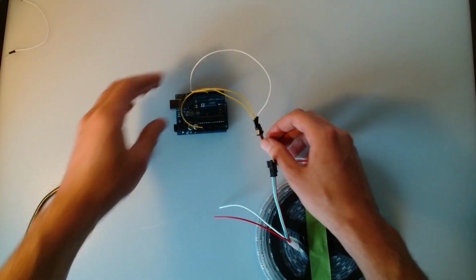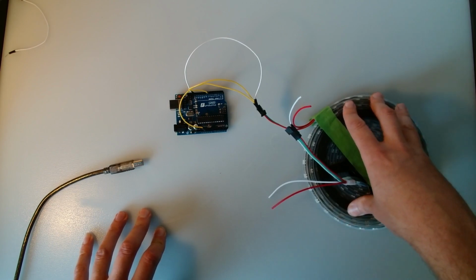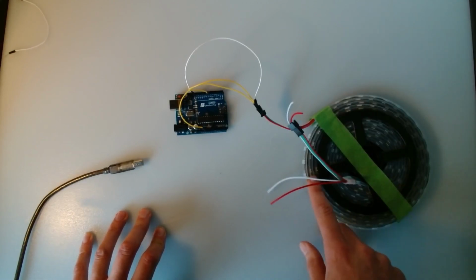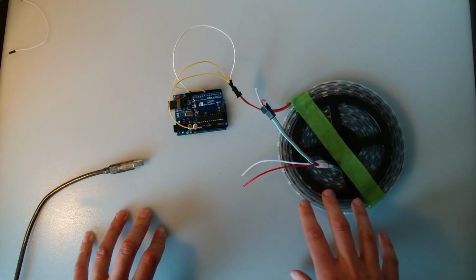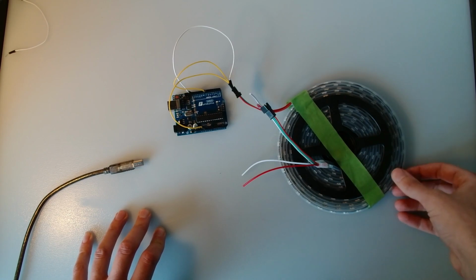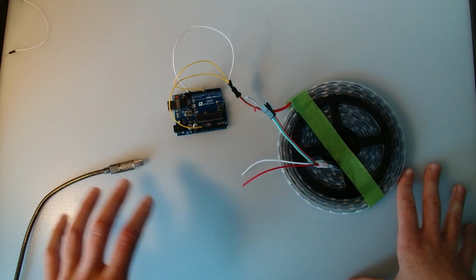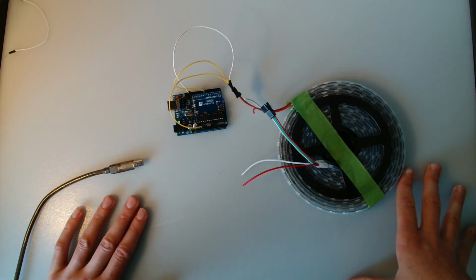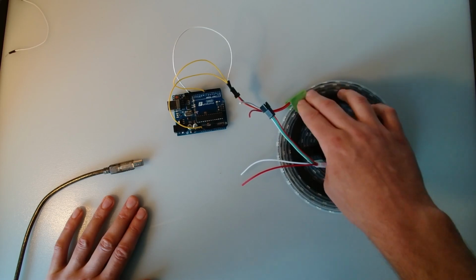There will be some comments that will say, well, hold on a sec, that's too much current draw for an Arduino. The way these addressable LEDs work is they strobe. Whilst it looks like they're all on to the naked eye, if you take a high-speed recording and slow it right down, you'll see that they're actually blinking. This is the same way that 50 Hertz household lights work, and this means that this Arduino is actually capable of pushing power to these fairly reliably, and we'll show you that in a minute.